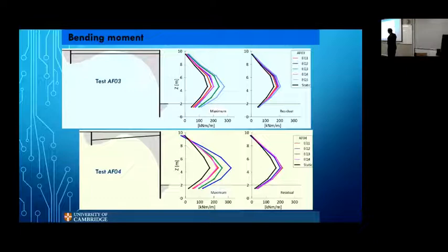And we can, of course, look at the bending moments and see that the important thing is what the magnitudes are. Obviously, the shorter wall has bigger bending moments compared to the longer anchor wall. The interesting thing for me is that earthquake after earthquake, we're applying 4 or 5 earthquakes, you can see the bending moments increase and stay. So the residual bending moment is always there and keeps increasing after every earthquake. So the wall kind of remembers that it has seen an earthquake and therefore it must carry this extra bending moment. So when you're designing these things, you need to design to withstand, obviously, the worst case situations.